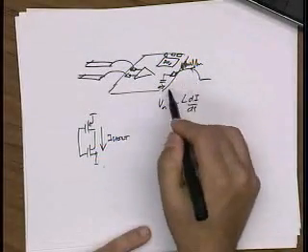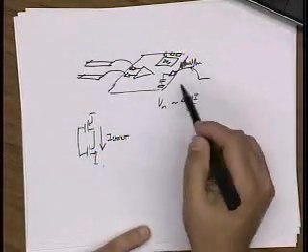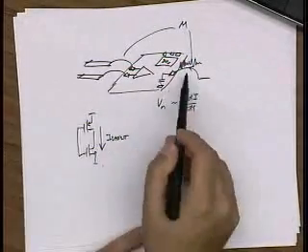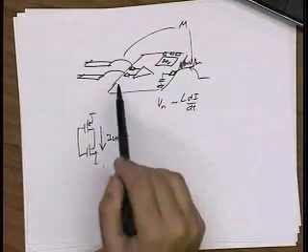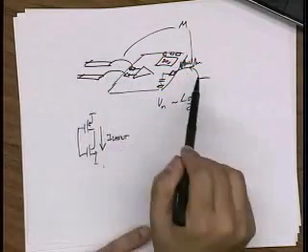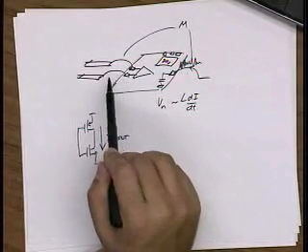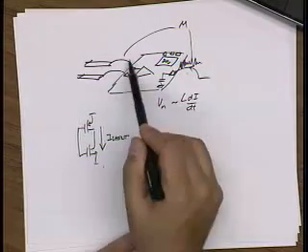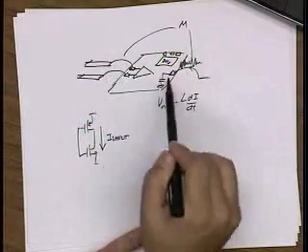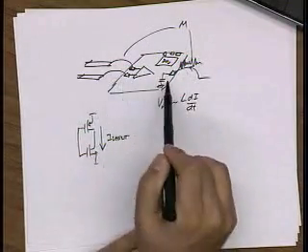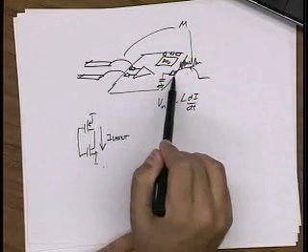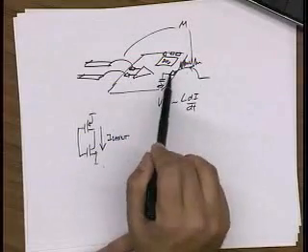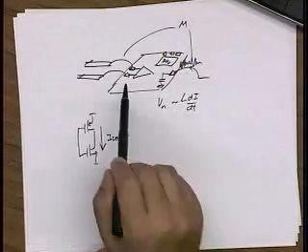And because this is a large current, it actually will generate a large magnetic field which will couple through the mutual inductance to the inputs. Now if I had a single-ended input, all of this noise would appear at the input of my amplifier and it would get amplified. Right? That would be terrible. But if my package is symmetric, then the symmetric component of the input gets canceled out as common mode. So it's only the asymmetric part that will generate signal.